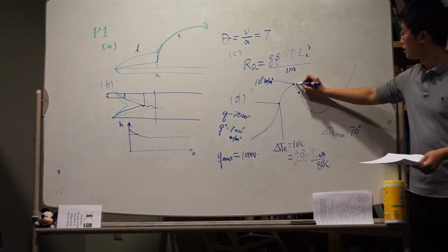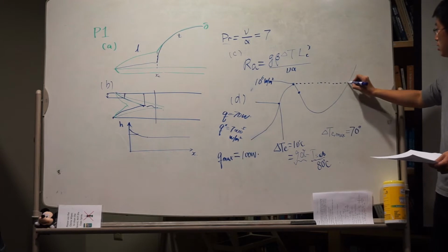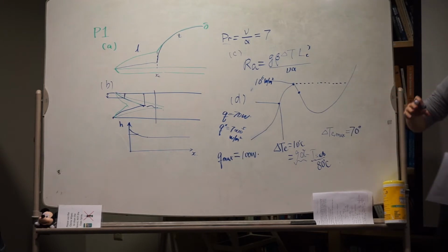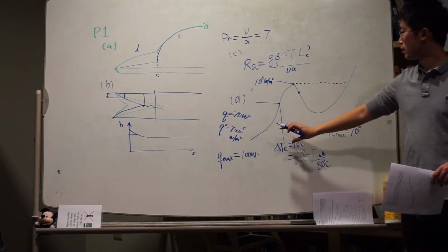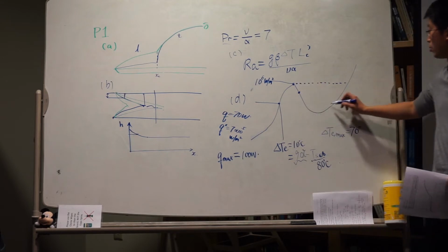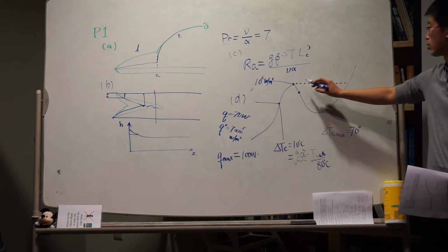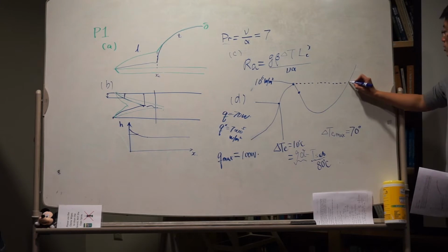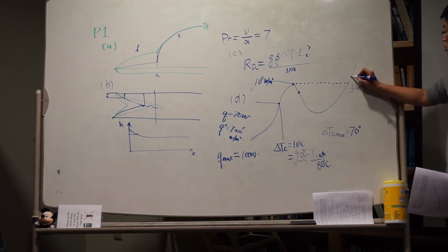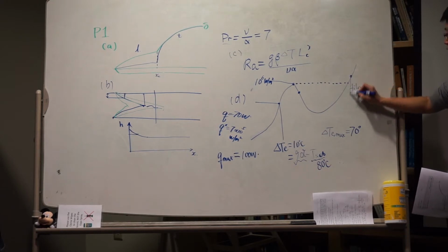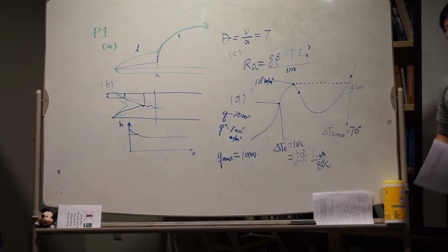It will be here, right? Say if we are controlling the surface power, the boiling will not undergo this part and will directly go to the boiling crisis and reach the film boiling part. It will be somewhere here, and this will correspond to a very high temperature.